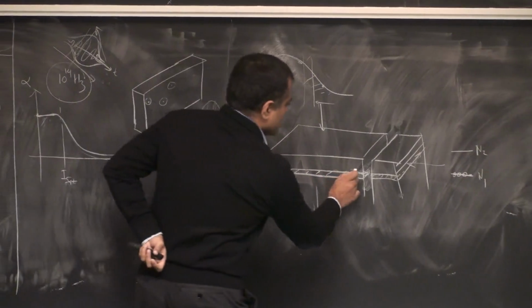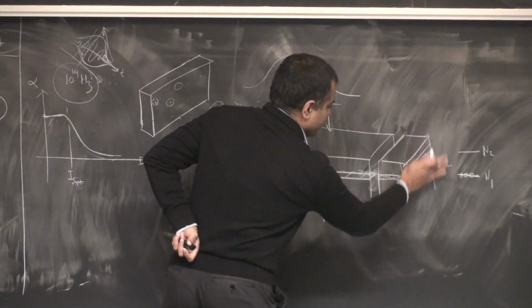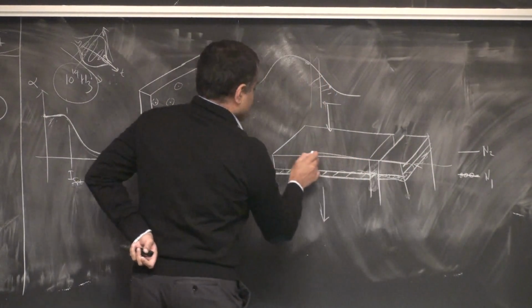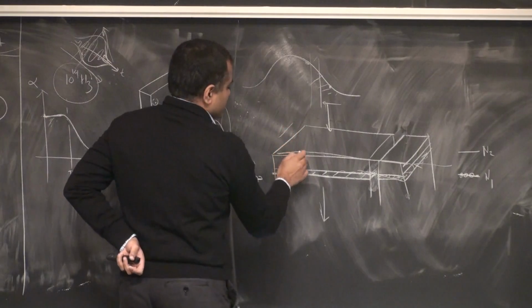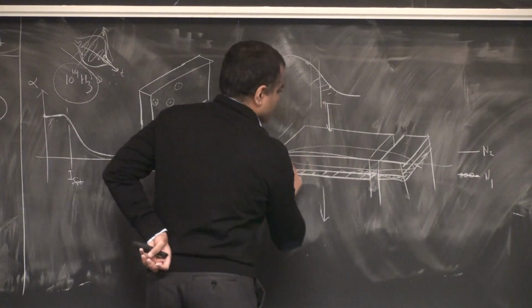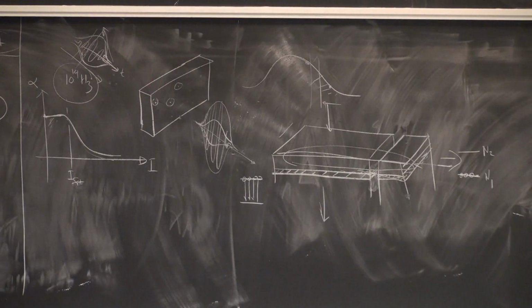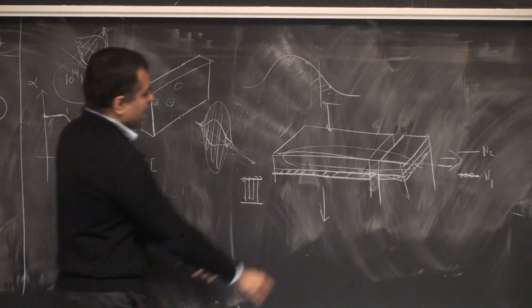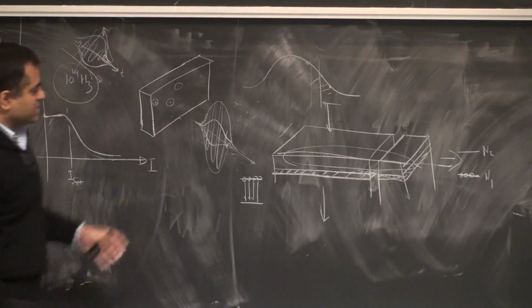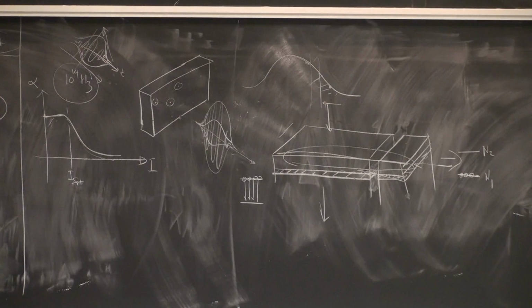So the light goes through here, and this is a cleaved facet, for example. It reflects, and maybe you can put one more, though generally people just put one. It goes back and forth, and the light that comes out from the end here is already mode locked. You don't have to do anything else. It's very simple in that sense. I'll talk about this in more detail later when we talk about semiconductor mode locked lasers.